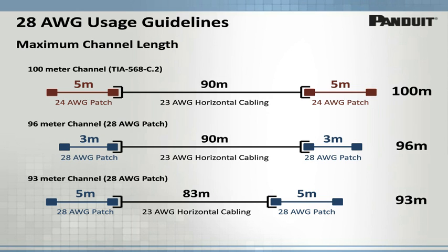You just have to remember that when you start mixing the gauges, that you do have to consider, basically, if you know that the other gauge is 24 gauge that you're working with, you're only looking at the incremental difference on one end. So the good news there is that now the channel length that you can achieve is even higher than what I've stated here. These are conservative estimates on the basis that you might use it in both places. But if you use it just in one, you actually can achieve a higher channel length.